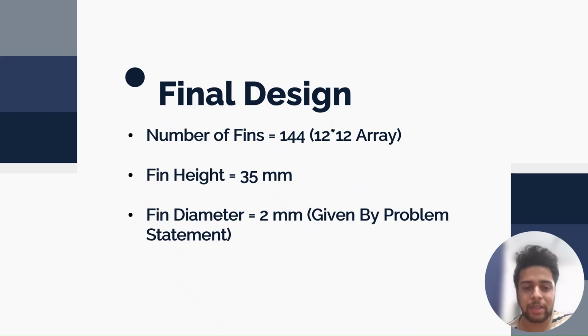Based on the parametric study, we have decided to keep the number of fins as 144, which will be a 12 cross 12 array, the fin height to be 35 mm, and the fin diameter, which was fixed, to be 2 mm.